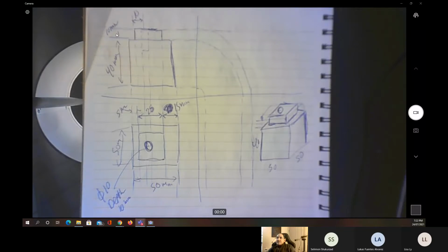The problem we have is that the depth of the cut is 10 millimeters. You remember that if this part is made of any material, we cannot get the depth directly to 10 millimeters, because this will either damage the tool if the part is hard, or damage the part if it's not hard. That means if this one is made of, for example, foam, like the one we used to use in the lab before, and I insert the cutting tool inside the foam by 10 millimeters and start to move it, it's going to damage it. So we always need to remove the material layer by layer until we reach the final